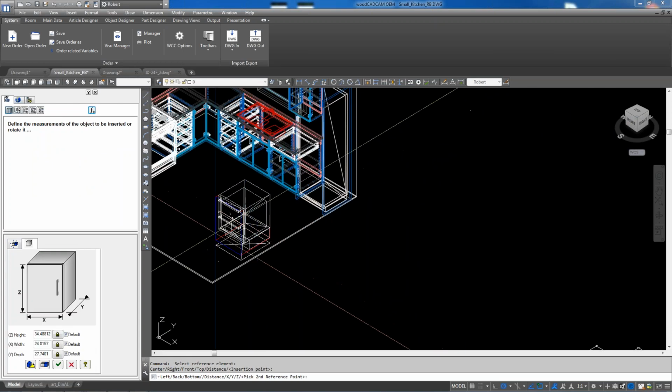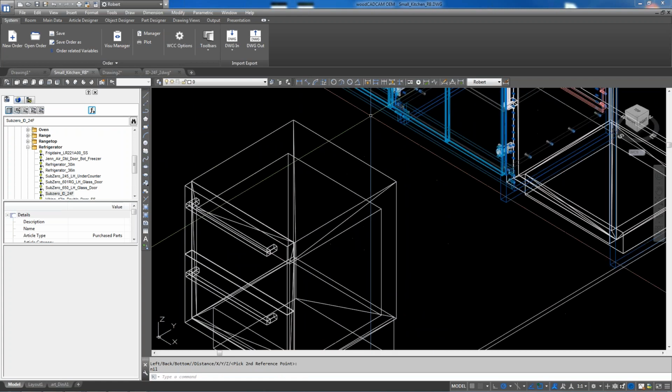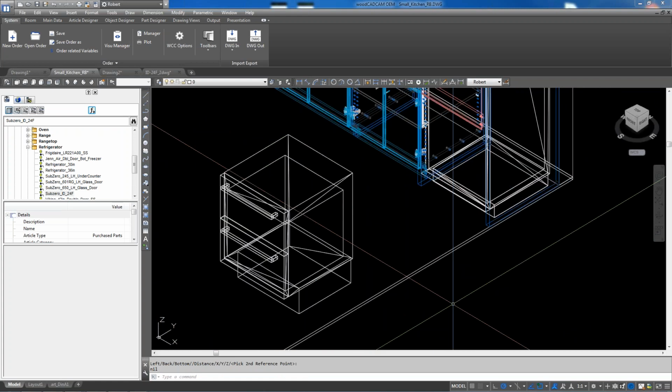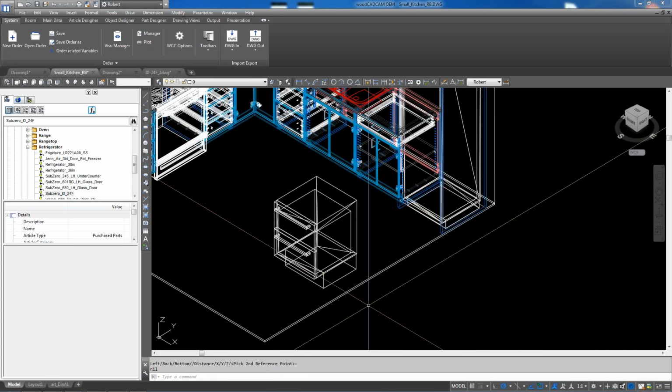That's it. So you do have to make sure that you explode. If it's already a block, when you open that drawing, make sure you explode that block and save it. And then whatever name, and of course purge out all the crap that's in that drawing, so you don't have any loose information. And when you save it, you just need to have another name other than the drawing. Otherwise, you get a circular reference.